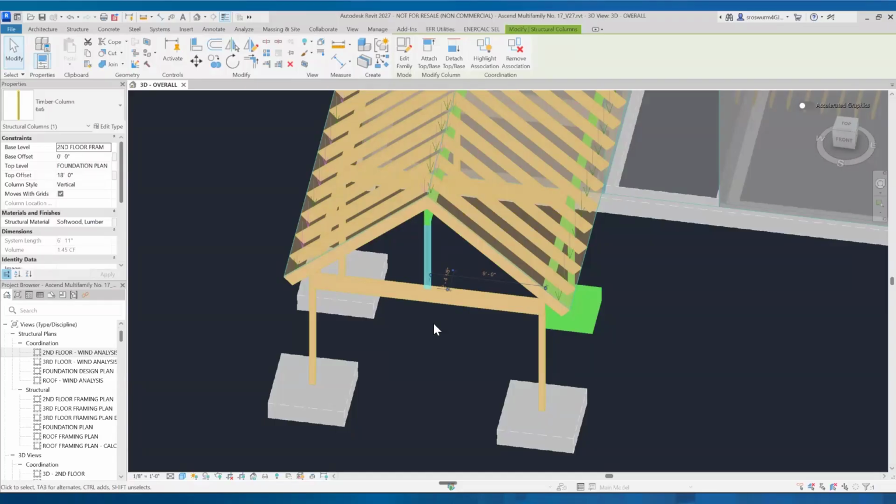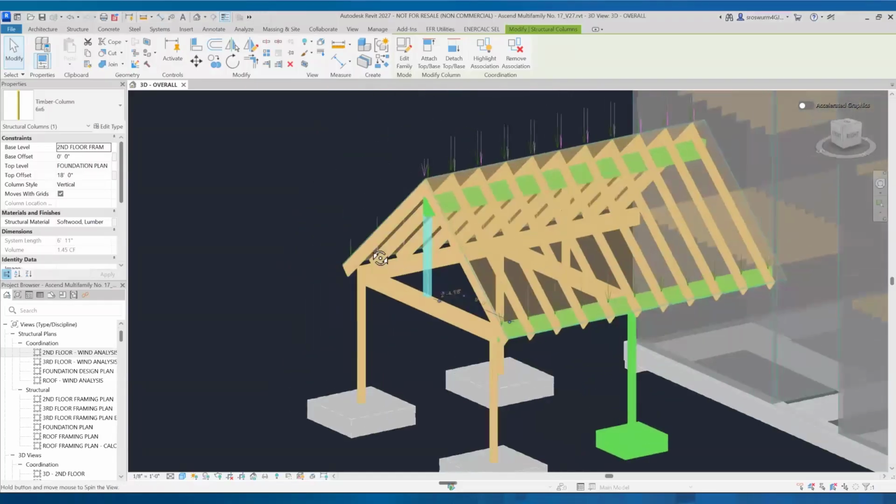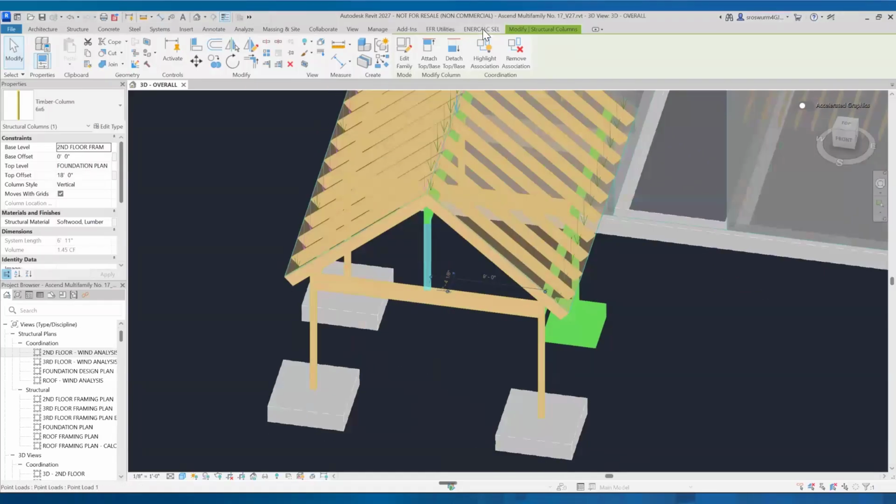So turning our attention back to the main entrance example that we went through earlier, just like we have the girder at the eave that we designed, we also have a girder at the ridge. The girder at the ridge is two-span continuous because we have these two king post configurations and the bearing wall at the face of the building. And so in my example, I've already designed that girder. It now has reaction forces.